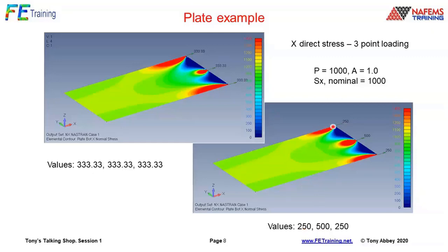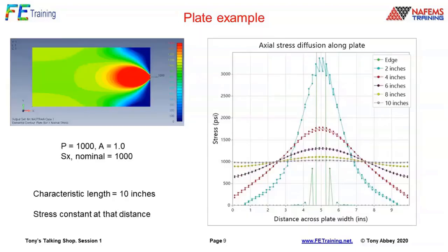We can't really see it here, but if we actually put little point forces all the way across here, which is not a good idea, we would drop the load at the corners by half, and then we'd actually get back to a good distribution on that edge there. Little points which are coming out as a side, but again, they're useful to pull out. So the bottom right is perhaps the best effort we can do with these point loads in here. But again, even then, that diffusion length has got a little bit better, a little bit shorter, but it's still about the order of the width of the plate. So we're playing around with different types of application.